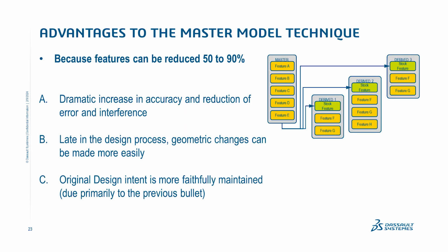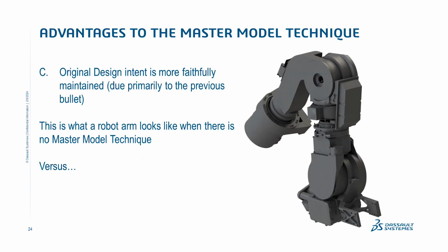So we talked about accuracy. The accuracy is dramatically improved because you have fewer independent design intents. You have a master design intent, and that really is a great reason to use master model. You can imagine also, when we talk about design intent, what happens if you have a team of designers working,